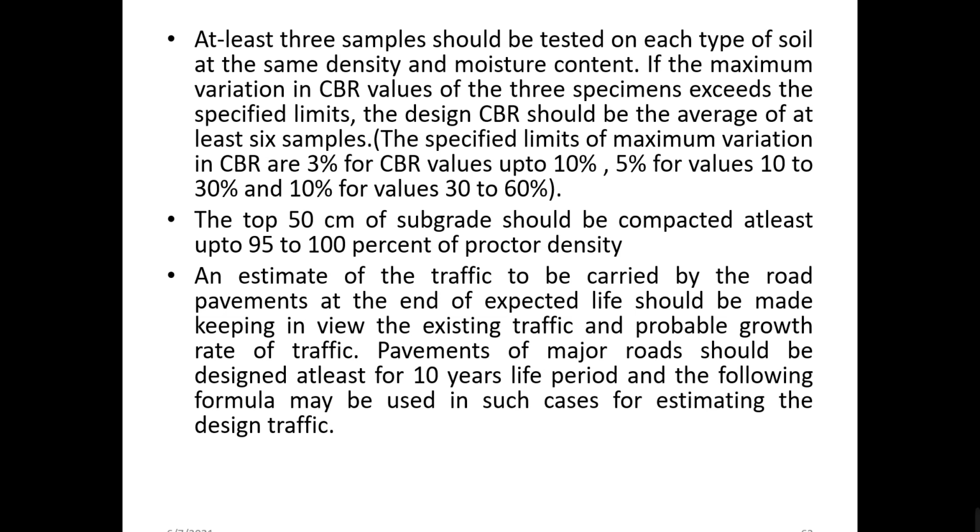Design life of pavement should cater service for up to 10 years, and the traffic condition should not be only the existing condition. It should also take care of anticipated traffic growth of the automobiles that could come over the road surface, depending upon which the thickness requirement of flexible pavement is going to vary, based on the traffic as well as design life of the pavement, and also the CBR values that could range from weaker soil towards stronger soil.